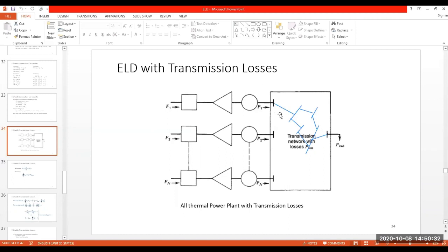And of course, whatever loss is occurring here should be some portion of the generation. It is not beyond the generations. So if this is 100 megawatts here, this is 200 megawatts here, and this is 50 megawatts here, the losses occurring throughout all these network elements should be some portion of this 100 megawatts, some portion of this 200, and some portion of this 50, right? So we can also represent these losses in terms of the power generations. Is this clear? Should I repeat?